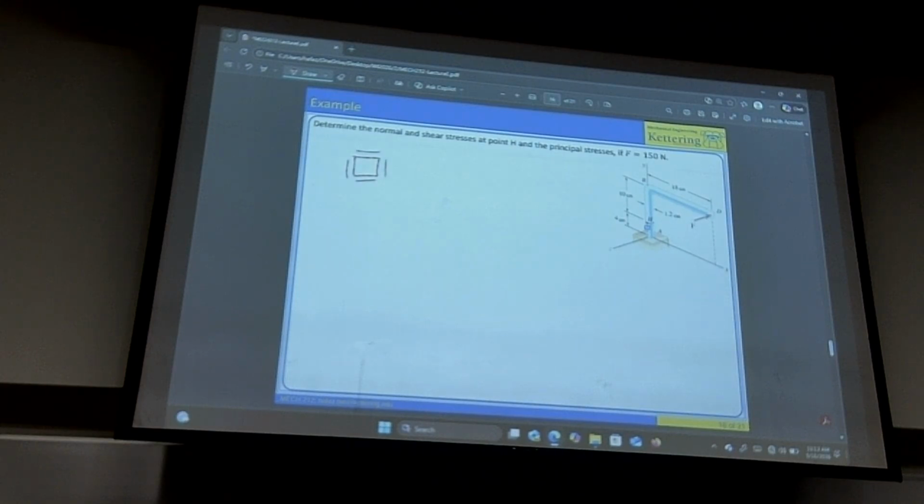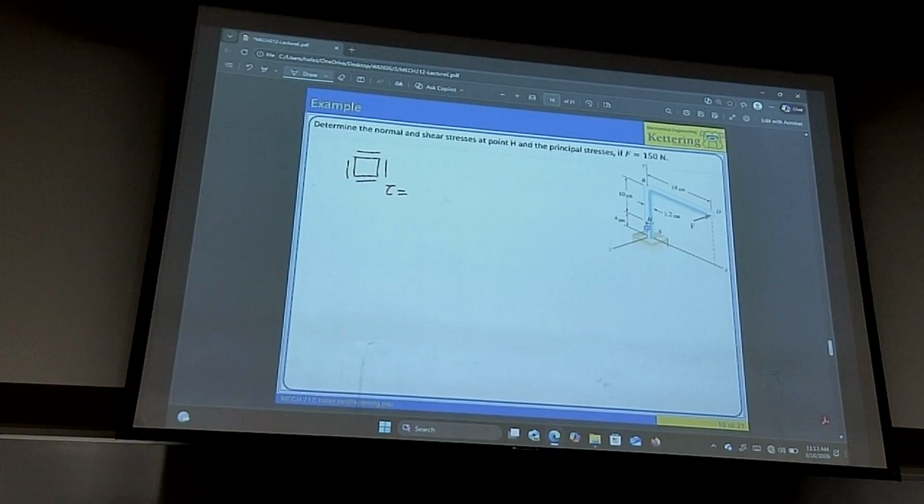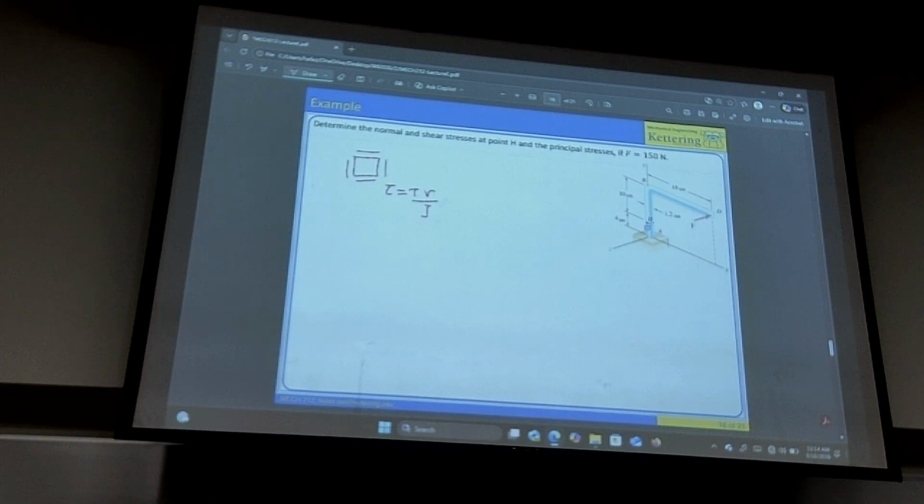We just did it. Yeah, right. That would be the torque times radius over J. All right, very good. You have that. Does it cause, actually, you gave me enough. Let me give you a point. Wasi, does this force create any bending? That's a solid geometry. Yes. About which axis? Look at AB component of it. Does it curl around?